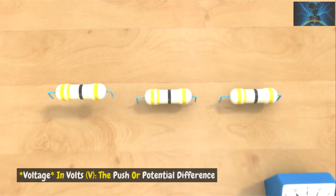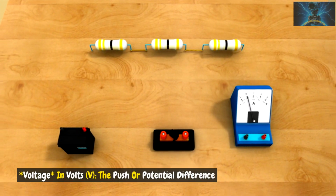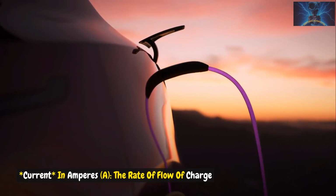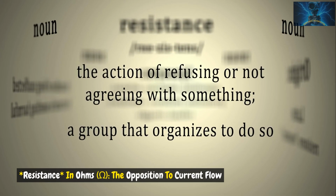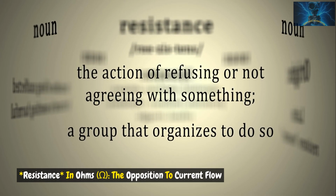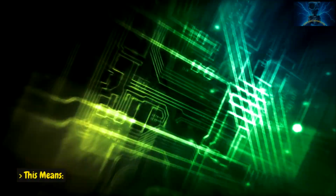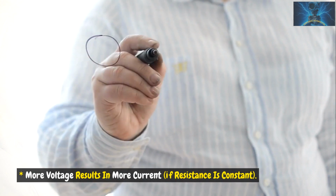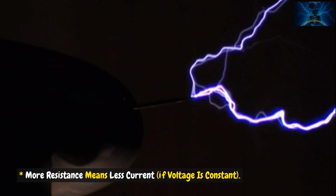Quantifying the flow. We define voltage in volts, V, the push or potential difference. Current in amperes, A, the rate of flow of charge. Resistance in ohms, Ω, the opposition to current flow. Ohm's law ties them together: V equals I times R. This means more voltage results in more current if resistance is constant. More resistance means less current if voltage is constant.